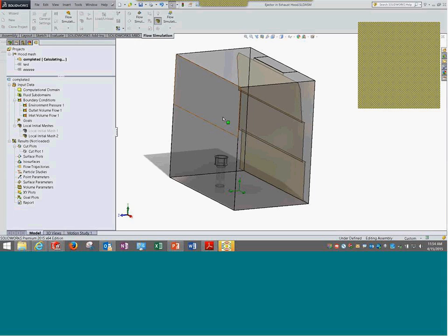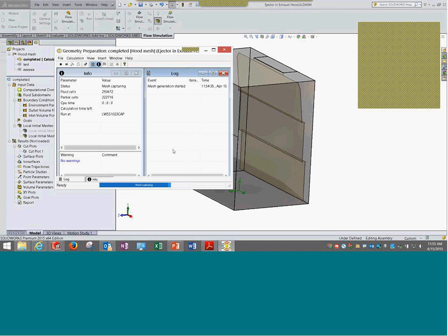However, in cases where you only want a refined mesh at a certain location, just get a component at that location, display it, and use it to control the mesh. That's it. In flow analysis, it is a bit risky to refine the mesh at the global level because we have a lot of elements and it can be complex.